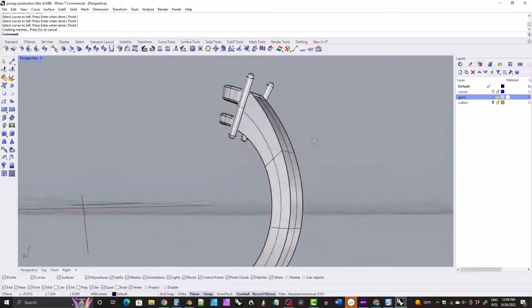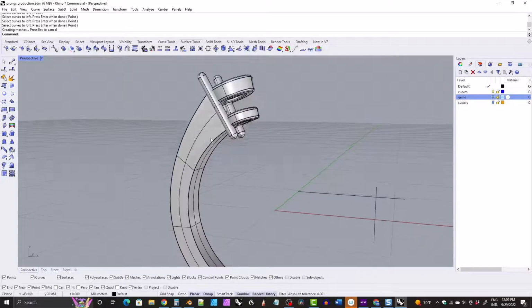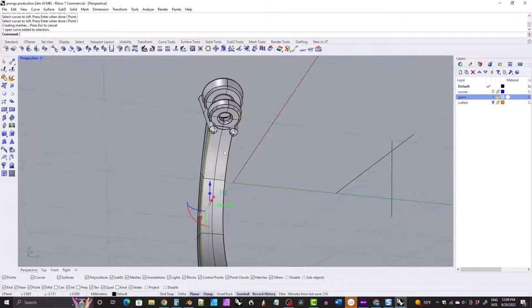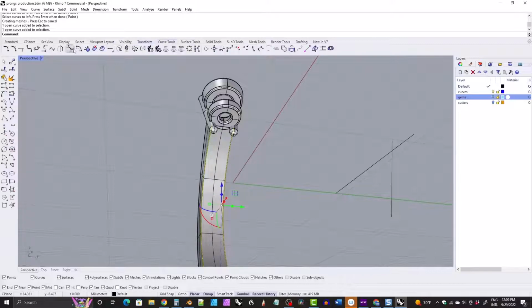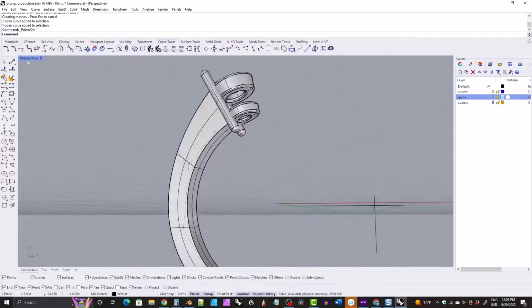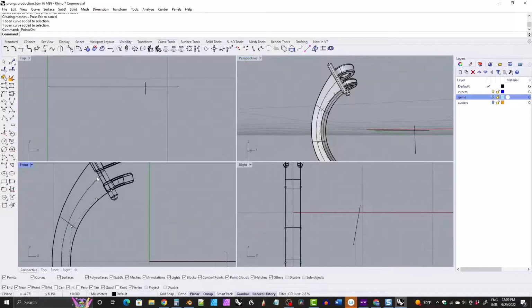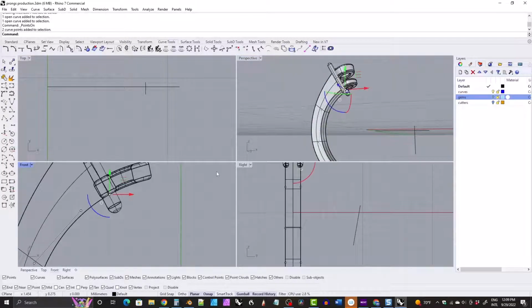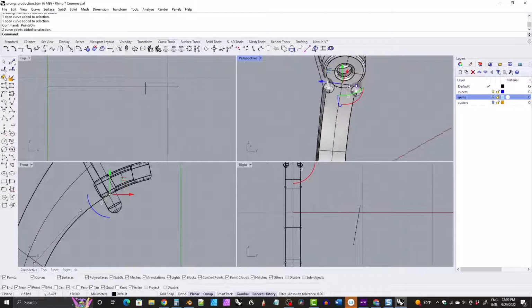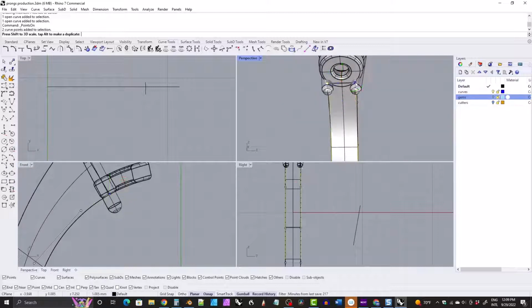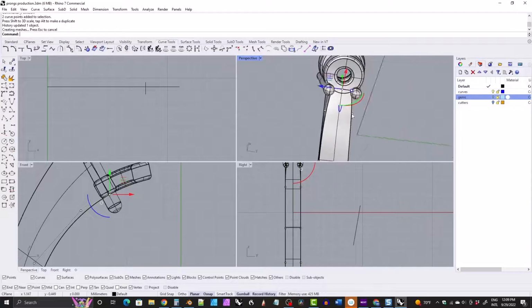All right. So you can either do that, and if you do it this way, when you make adjustments, you'll need to select both curves, turn on your edit points, and then come here to the front view and select, say, those for instance, and you would use the scale function to scale them both in. All right. And you would grab maybe these and scale them in as well.